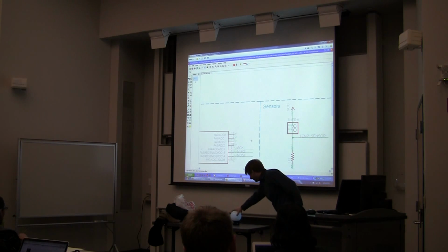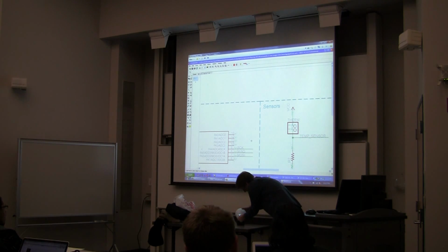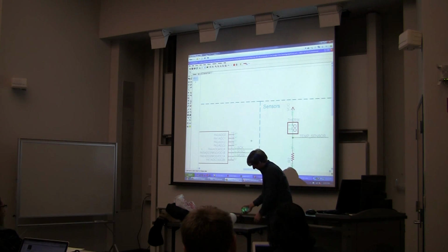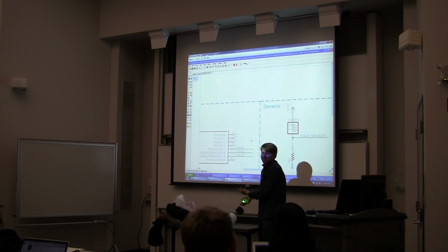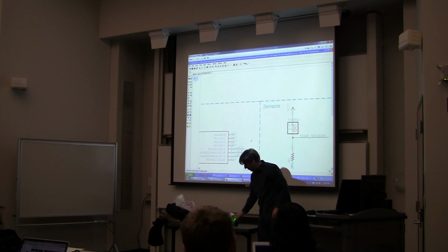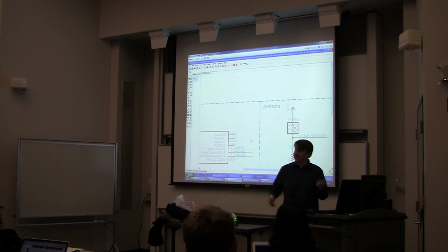And if you'll notice, on this little circuit board, these LEDs do get a little warm, and so the thermistor is hanging out way down here, just sort of on the longest legs it can, just sticking off the board. Because they do sell board mount thermistors. They look like a resistor because they are resistors. But this way, we're kind of getting it far away. And this is where it helps to start thinking about your housing and sensors.